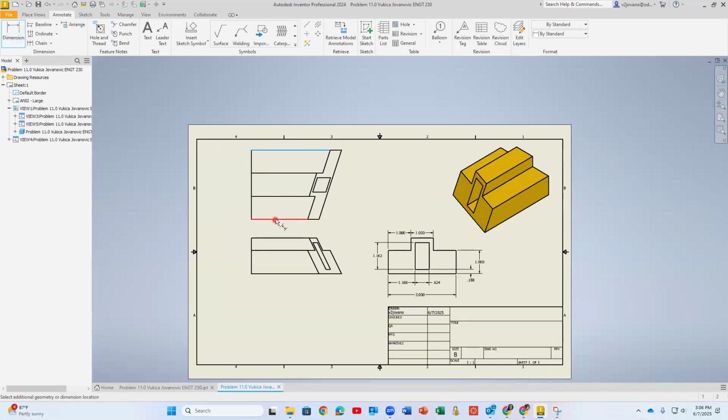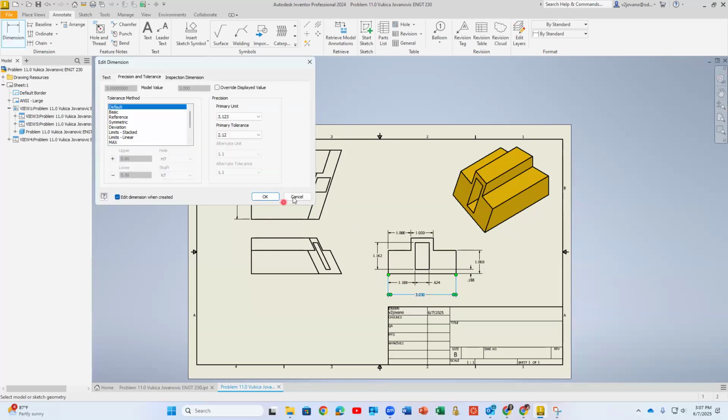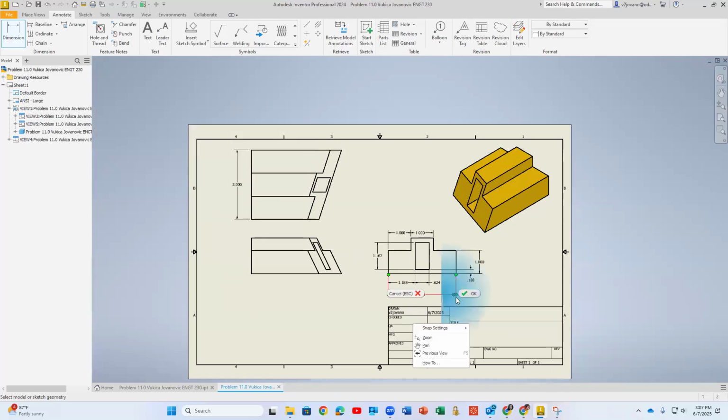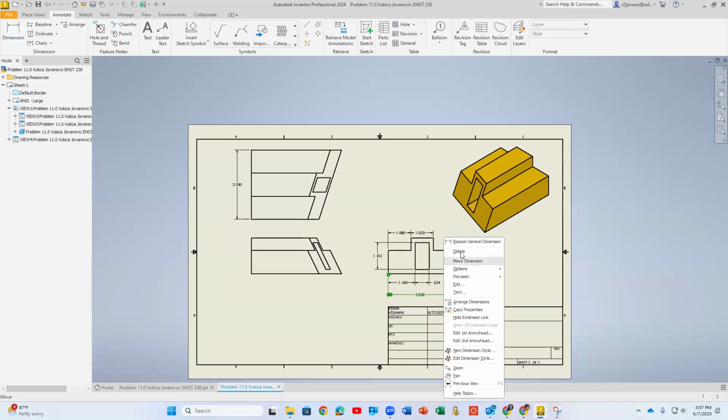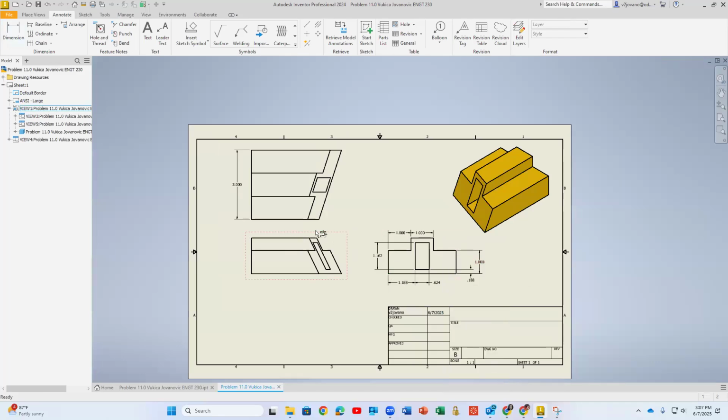Okay. And basically, I can use these two just to move something there so they don't look empty. It's better dimensioning practice just to have at least something in each one of them. But when I moved one there, I should remove one from here. Right click, delete. And then the overall height can be here because there's nothing happening there. And maybe we can add the angles, we can see maybe this angle.